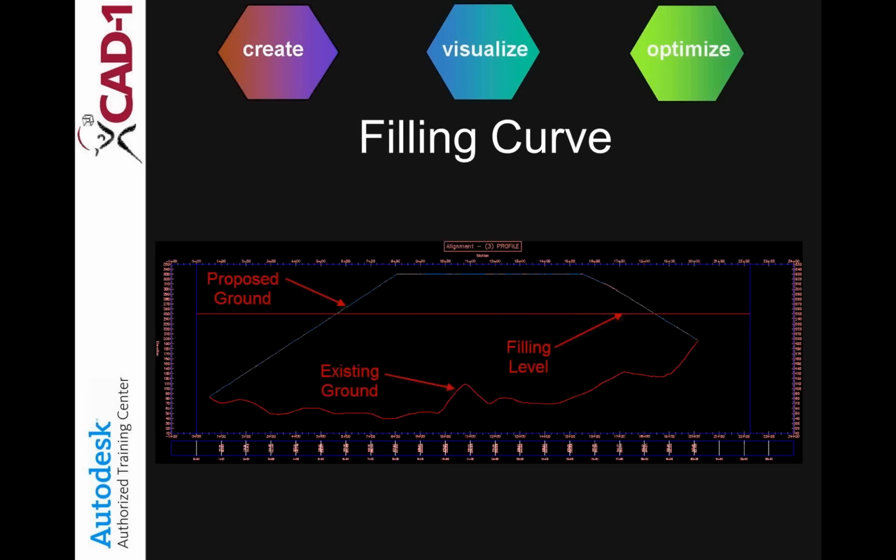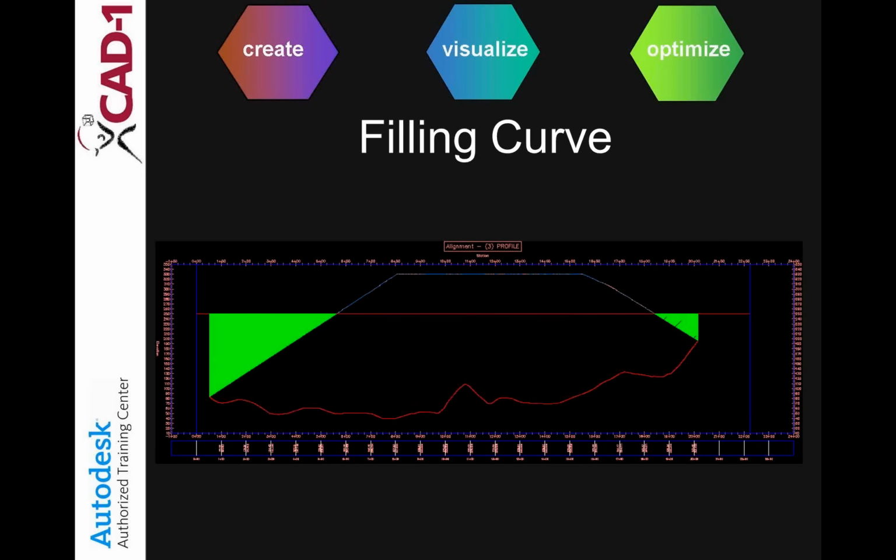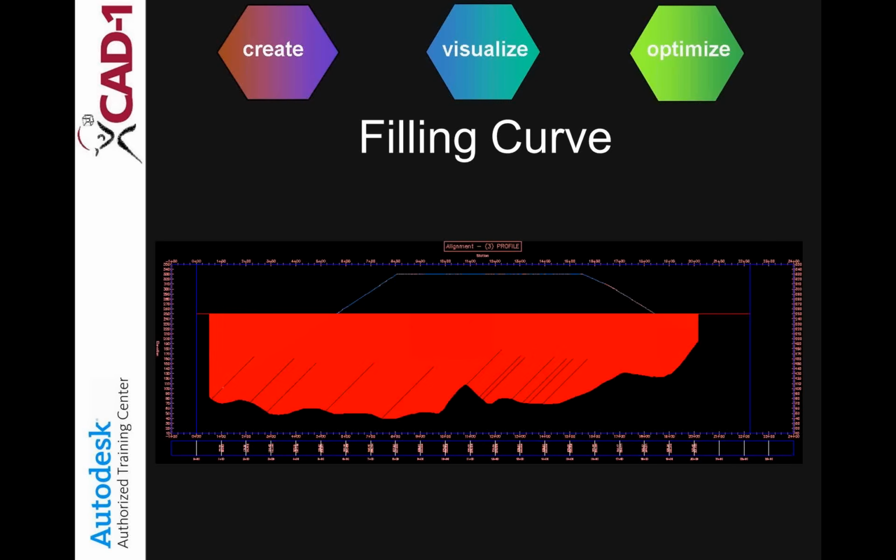And here's the approach I came up with. Now, just to give you an idea of what we want, this is the volume that I need to know. What is this particular volume here? Now, there's several things that I can calculate. I can do a volume calculation between this elevation that I want, which I'm going to call the fill level, and the design. So these numbers I can calculate. This is the excess stuff. I can also calculate a number between the fill level and the existing ground.